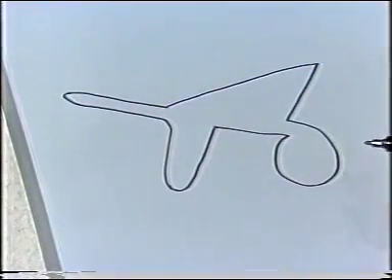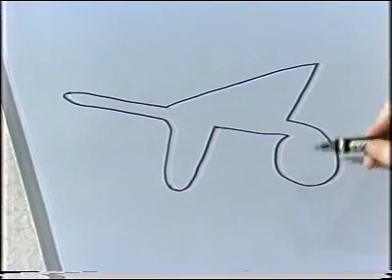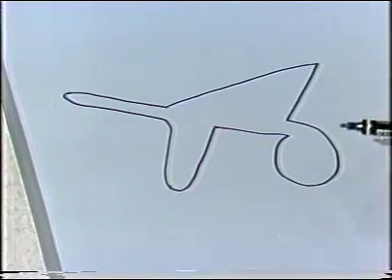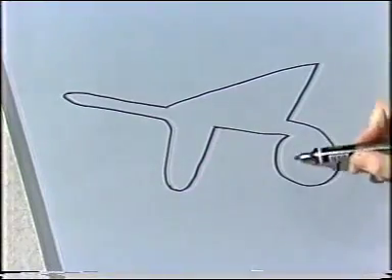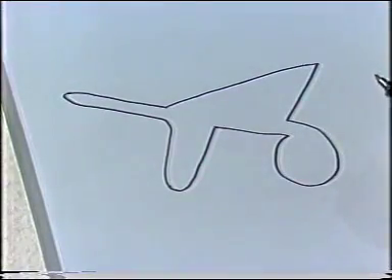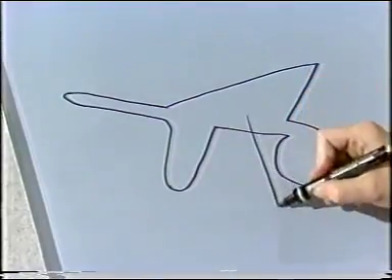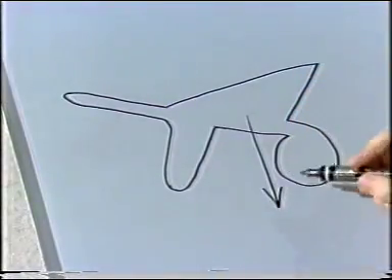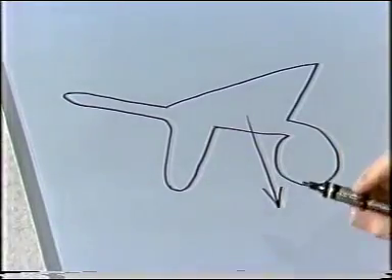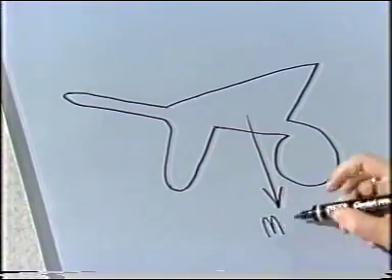I'm not interested in the interactions between the wheel and the main part of the barrow either, but I am interested in the reaction force at the floor which supports the wheelbarrow. No internal details are needed. We're only interested in the forces acting on the body, not the ones acting within it. So, for example, I don't show any wheel bearing forces. Next, I mark all the forces acting on the body. The weight force acts in a vertically downwards direction through the centre of gravity, which is the length A from the front contact point. It's equal to mass times g.